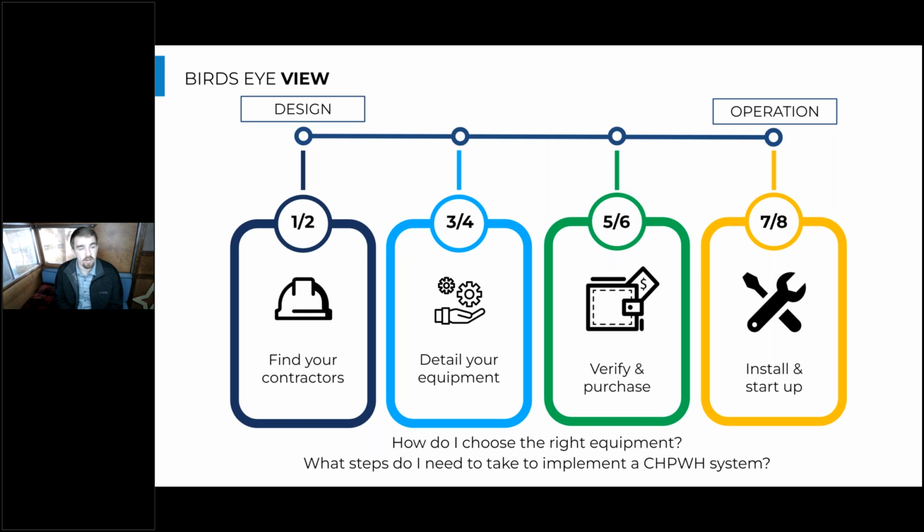And then we talked about how to detail your equipment and the little factors that will change how a heat pump operates in the scope of the entire system, and what you need to make sure you lay out per a specific manufacturer, in coordination with their reps and their documents, to make sure you have all the boxes checked as part of your design.